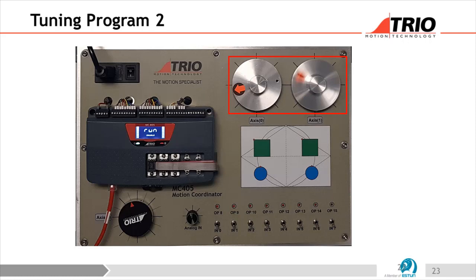So in order to make them stable, with this particular test we're doing now, or when we use these rigs, we actually have to set a D gain, and it's nothing to do with PID, it's just the fact that there is no speed loop in the drive, but you've got to set a D gain to make these actually work, and probably 30 is a good value.